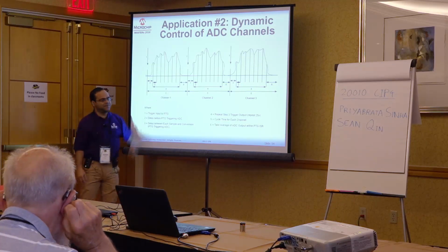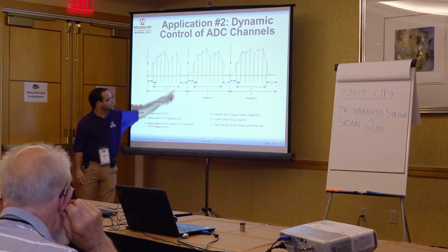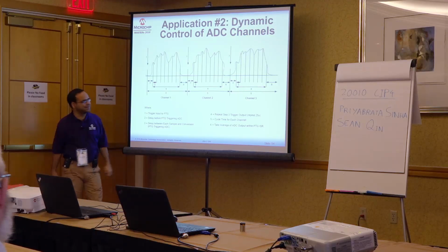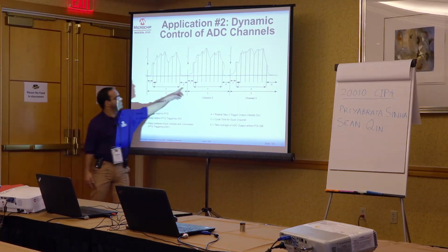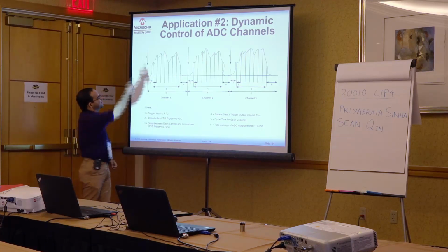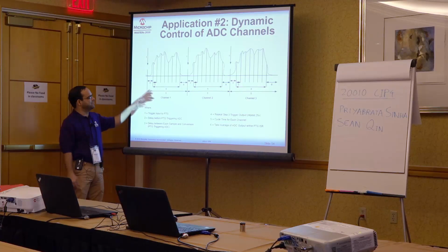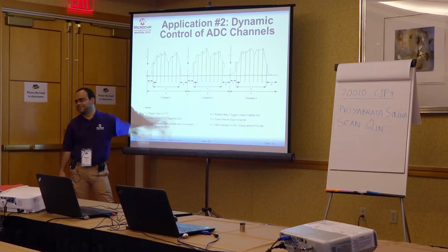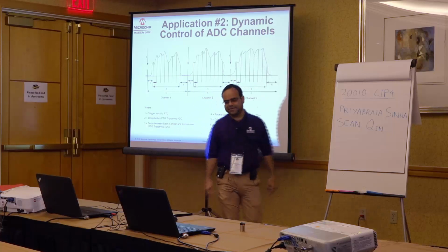And once that's done, you need the CPU to average out that data, right, the conversion results. So it generates a trigger and a PTG IRQ basically, so the CPU can service that interrupt, compute the average, and then it gets the next trigger. And the same cycle repeats, but in this case you have noticed that the PTG would have changed the analog channel selection. So it's now sampling a different channel. The next time it's sampling a different channel, and so on.